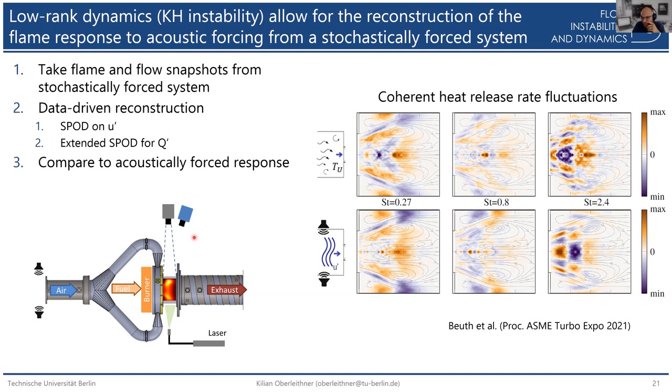data-driven reconstruction. And we're looking here at heat release in the combustion chamber, so heat release modes or coherent heat release, and you can see that there's quite a clear correspondence between the two. So this is actually quite nice because it gives you a possibility to determine a flame transfer function from naturally or stochastically forced data. And that is important particularly for running these very large scale rigs, because acoustic forcing in such a rig is a very, very difficult task to do.